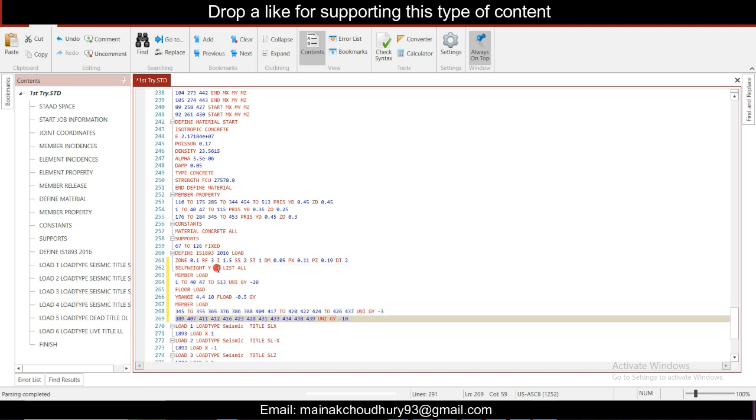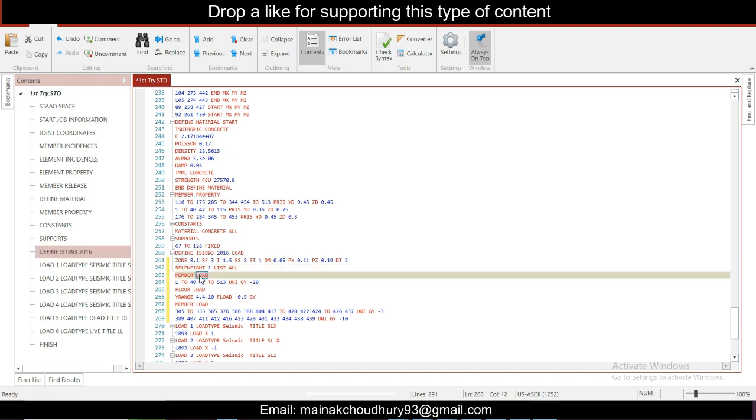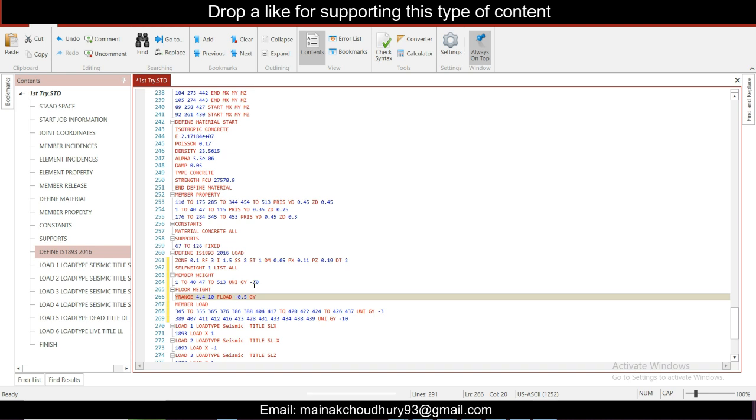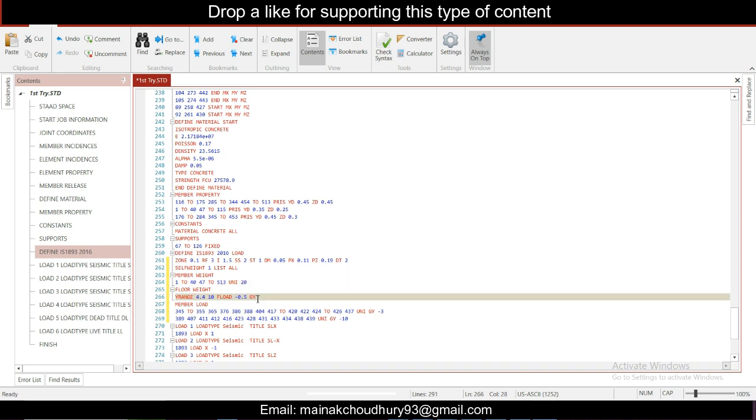So Y and -1. Remove member load. Instead of member load we'll write WEIGHT, because it's the seismic mass source. This is also WEIGHT, seismic mass source, and there is no direction here, GY, 0.5.